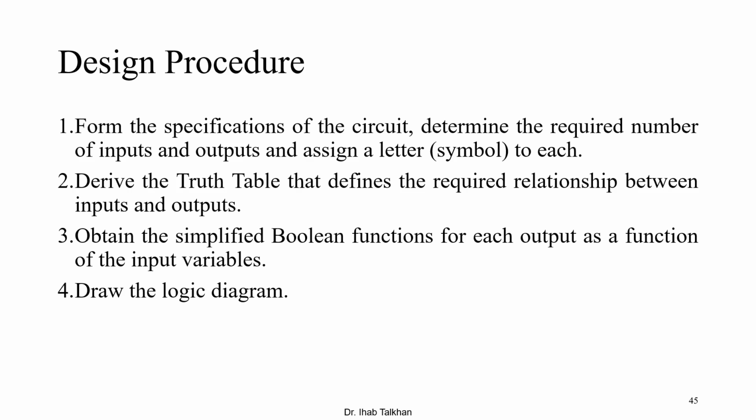After that, you need to obtain the simplified Boolean function for each output as a function of the input variables. And at last, you need to draw the logic diagram. These are the steps to design any circuit you're going to work with in logic design, or any other circuit, by the way. It's not necessarily logic design; this is a generic way to solve any problem, whether digital or analog or whatever.